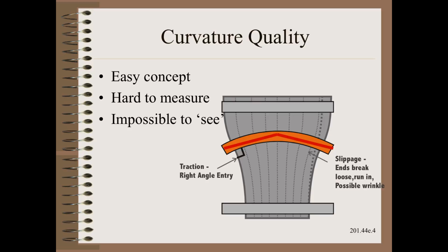So difficult that when I worked for Beloit as a winder designer, we had to develop and teach the bowed roller manufacturers how to check this so that our equipment performed as good as possible. As a final observation, the issues we discussed here are also equally true for other spreaders and, most especially, bent pipe spreaders.